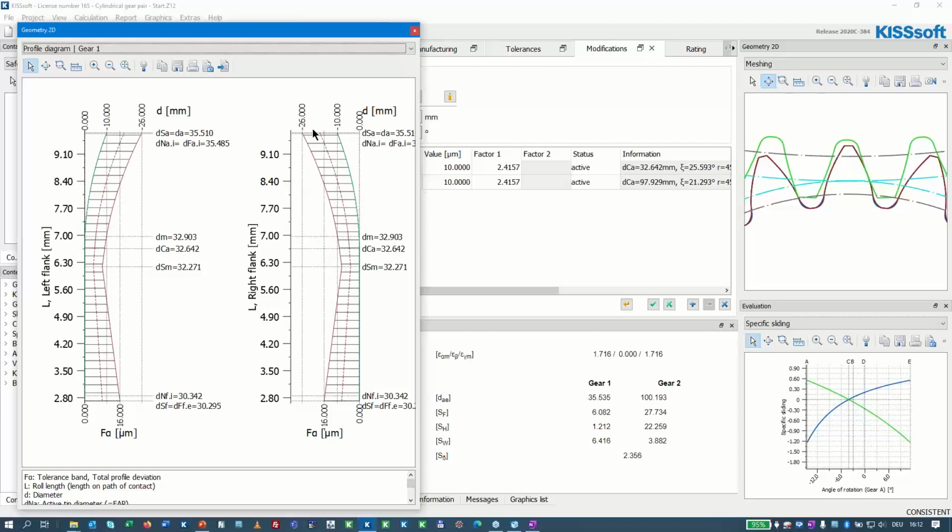Still, on average, most of them will be near 10 microns if you think of a normal distribution. So if you say that this range from 10 to 26 microns constitutes a 6 sigma range, meaning plus 3 times standard deviation on one side, minus 3 times standard deviation on the other side, then one standard deviation is 26 minus 10 divided by 6.